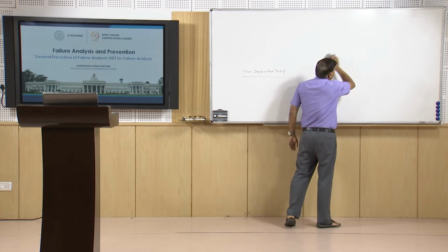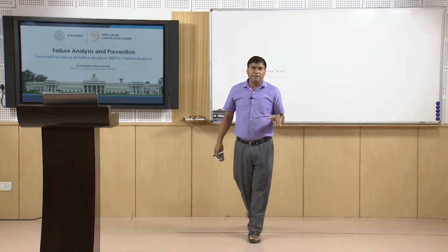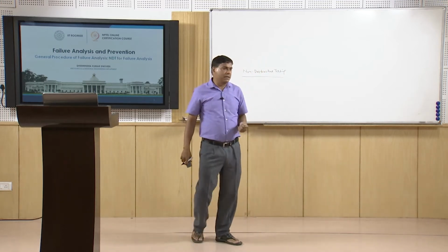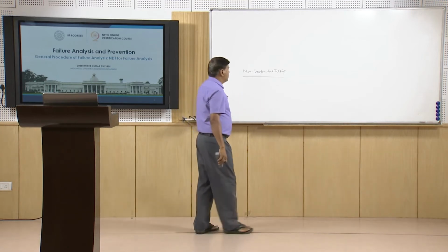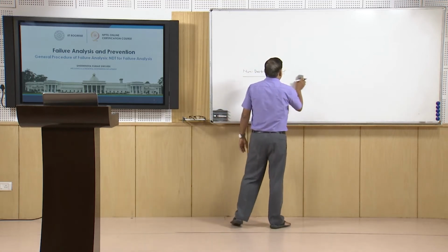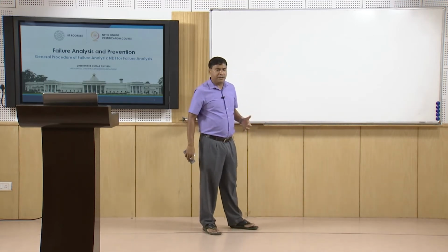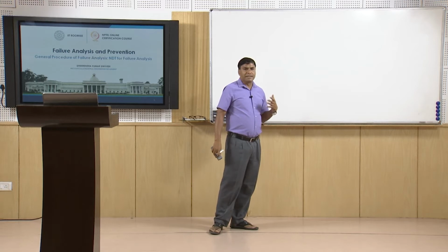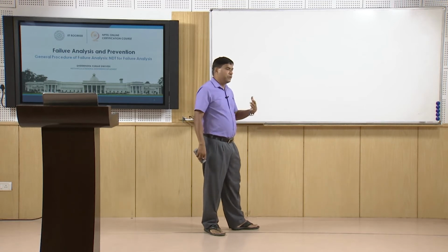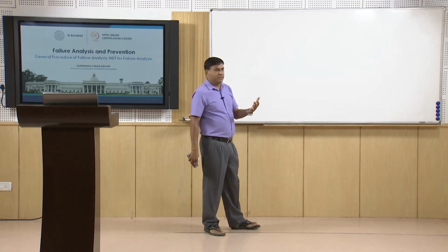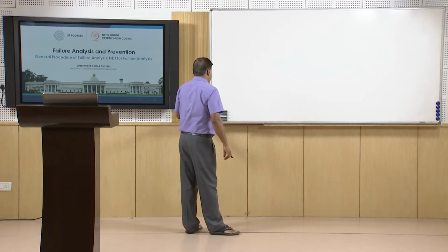One, we are able to identify and establish the size, shape and the type of discontinuities, and the location where they are present, and then efforts will be made to relate them with the failure. The second one will help to estimate the kind of load, stresses, and strain which have been induced as a result of the loading during the service. That can be related with the possibility of the normal load or abnormal load, accidental load. So, now how is it conducted?